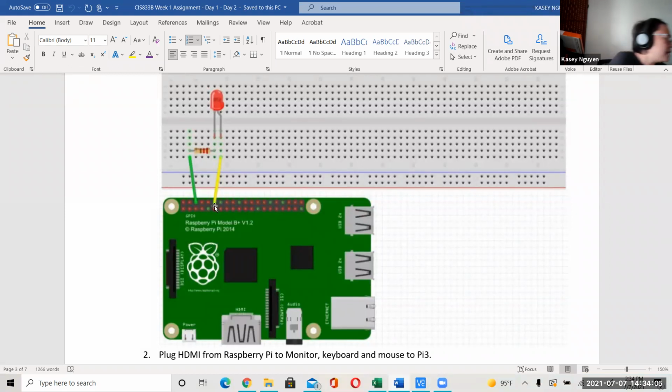And so when we plug that in, you just count the pins on your Raspberry Pi. So when you plug in the top part with the fan, you just have to give it the 5 volt or the 3.3 volt and the ground. Okay. Any questions?